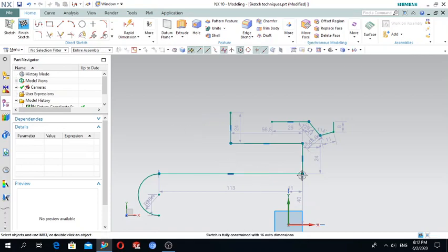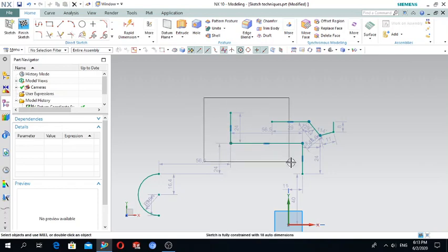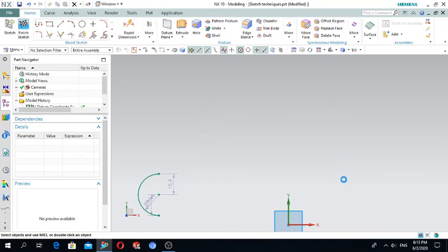To delete the created lines, select them and press the Delete key on the keyboard. To select more than one line, click multiple line segments. The lines will be highlighted. You can also select multiple lines by dragging a box from left to right. The lines are highlighted and selected, then press Delete. Also delete this arc. So this is about the arc command.